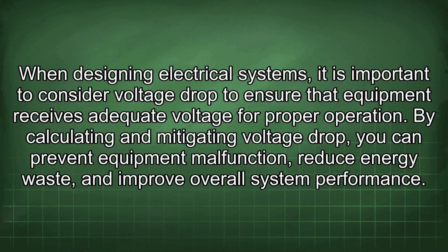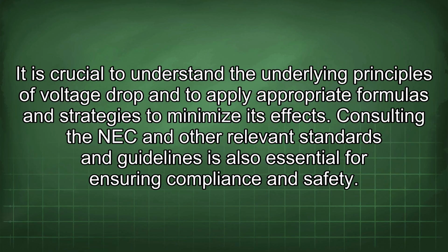When designing electrical systems, it is important to consider voltage drop to ensure that equipment receives adequate voltage for proper operation. By calculating and mitigating voltage drop, you can prevent equipment malfunction, reduce energy waste, and improve overall system performance. It is crucial to understand the underlying principles of voltage drop and to apply appropriate formulas and strategies to minimize its effects. Consulting the NEC and other relevant standards and guidelines is also essential for ensuring compliance and safety.